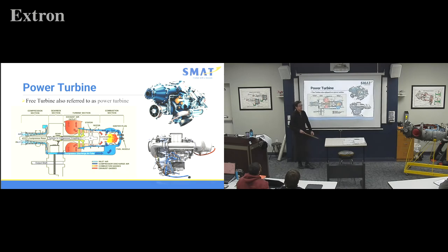Is the expanding air part of the pressure deal, or is that just increased velocity? Increasing velocity because of design. So it's expanding, but not more pressure, because rather than expanding and having nowhere to go, all the ducts are transferring that energy into velocity. And the rotor and stators are extracting that energy as soon as it's coming off our combustor. So we're extracting energy, shoving pressure, so that's keeping it going.